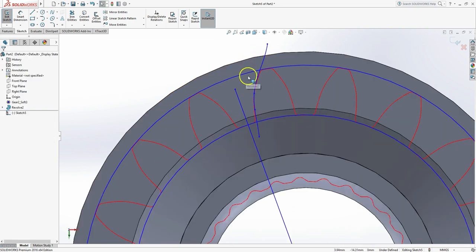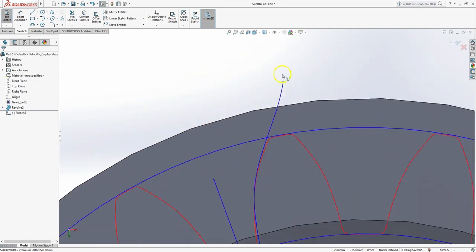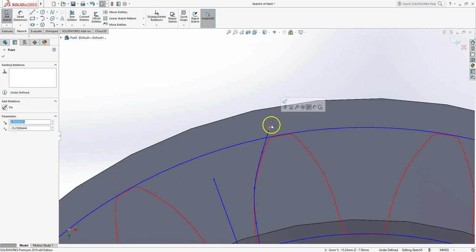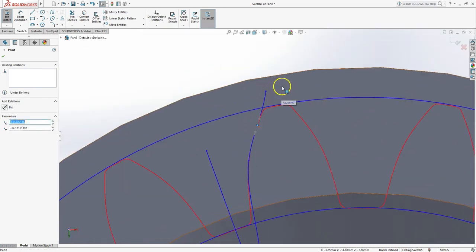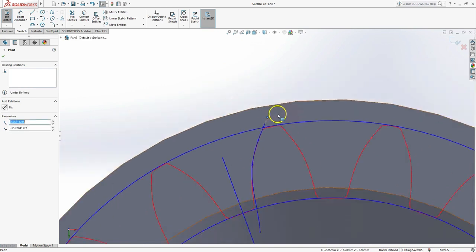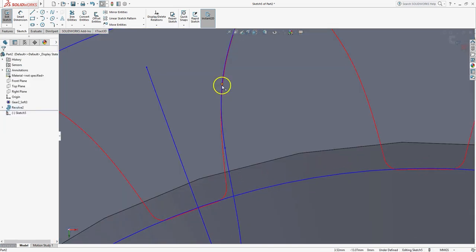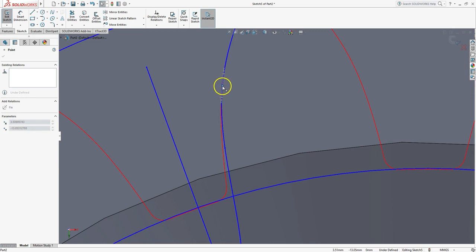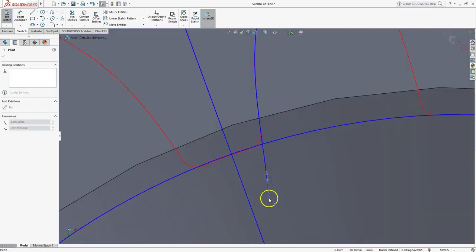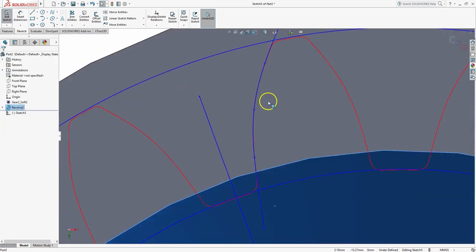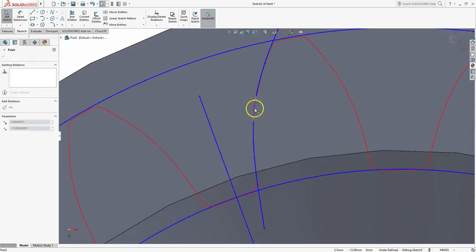You're going to get splines that are pretty close, probably good enough to run a gear, but if you're really picky about it and you're really using that to define the shape of your broach, you're going to want to use this equation-driven curve to do that. But let's go ahead and pull these into location. There we go. So you'll see I'm just kind of adjusting this until it fits extremely tight to the original curve.